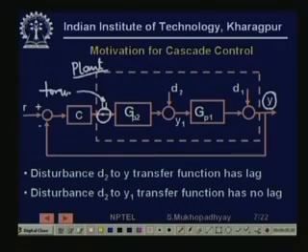So you give, what do you give? You change the electrical voltage at the terminal of the motor. So the voltage, suppose it's a DC motor, so basically you change the armature current. If you change the armature current, then what you change is torque. So basically the input that you are giving is torque. Now here you have torque, and here you have position.